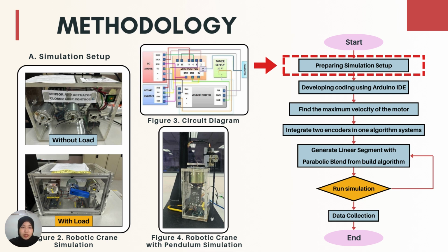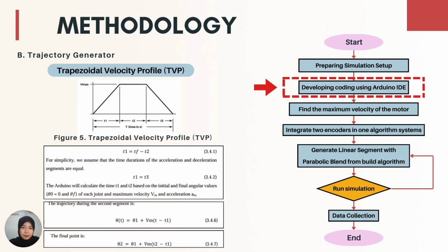Methodology. So we started by preparing our simulation setup. We have two simulation setups: the first one is the robotic crane simulation, and the second one is the robotic crane with pendulum simulation. Both of these simulations we integrated with the Arduino Uno and other components such as the motor driver, power supply, the encoder, and also the DC motor. Next, we developed the coding using the Arduino IDE.